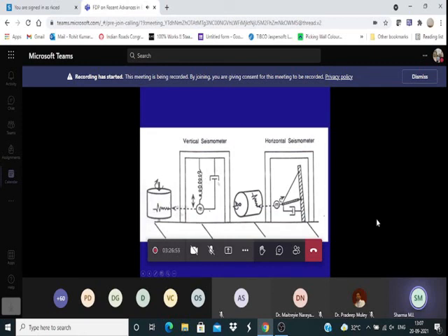So the modern seismographs have the mass and the damping, and then it is a spring mass damper system. You can go for the equations, but you know that as per the mass spring system, the length of this and the weight of this will decide the frequency or the natural period.